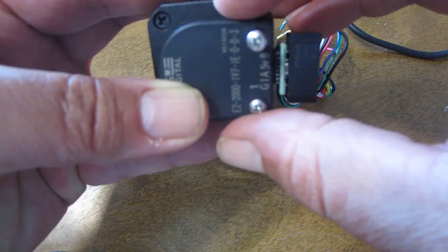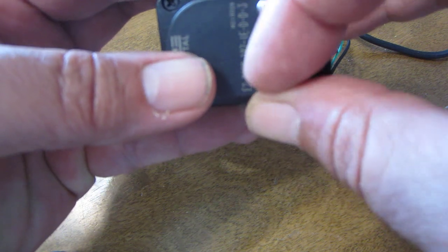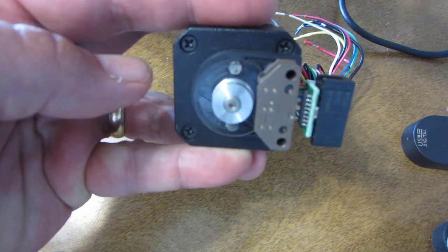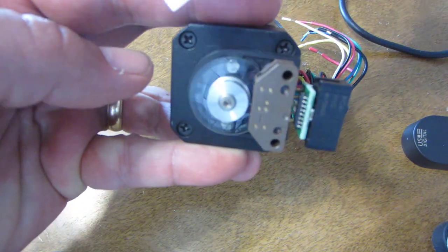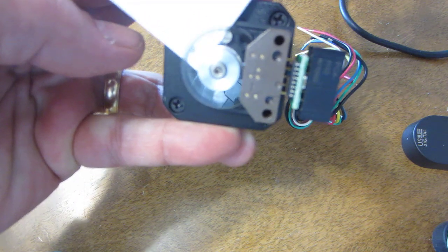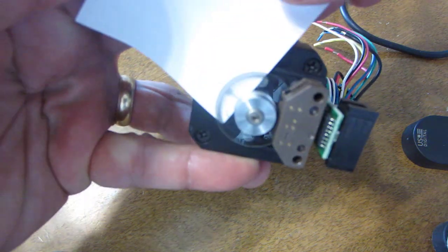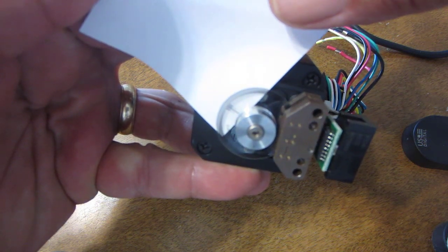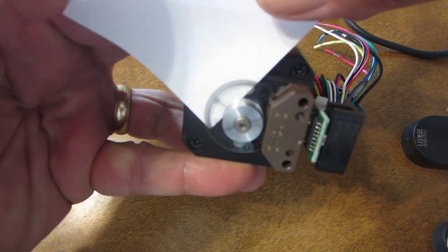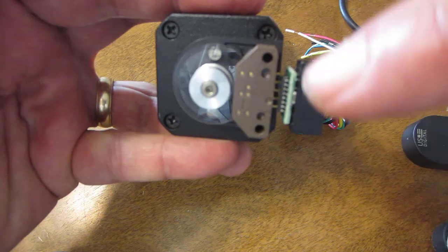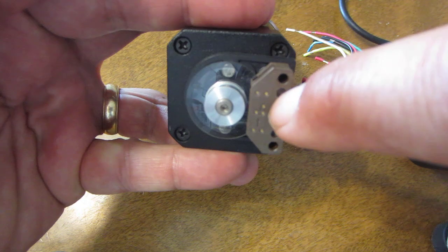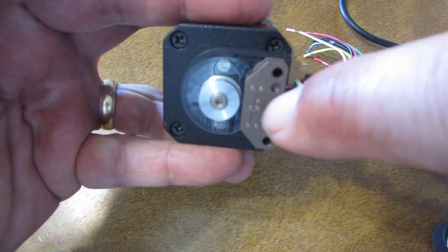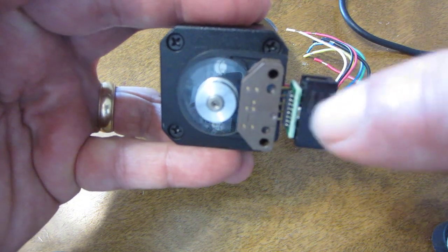So I'm going to pull the cover off, let you take a peek at what's below. You can see the Mylar encoder wheel. It's clear and it has some lines on it, and you can actually see the index channel as well, but on the outer perimeter there is a sequence of lines that are read by the motor encoder head. Here it's got A and B as well as the index light sensors built into the reading head.